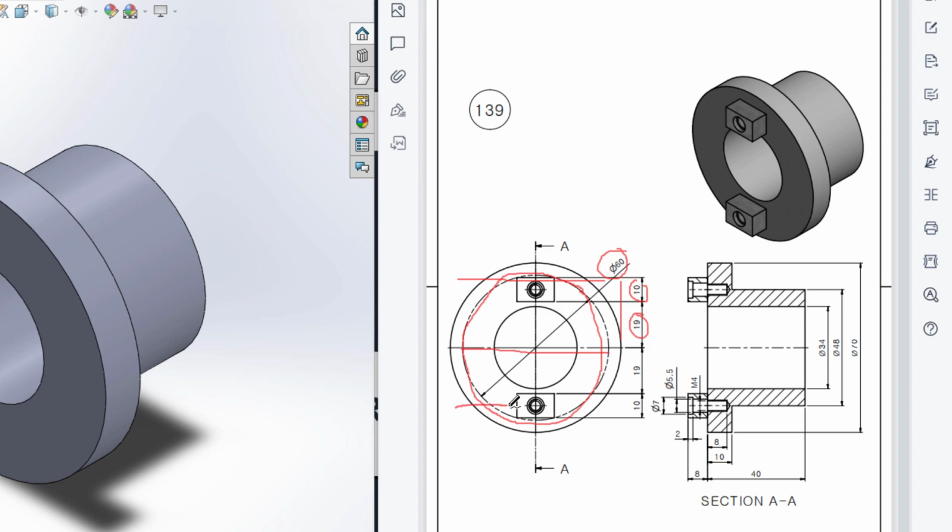I will also draw another offset line here, and this distance will be 19 plus 10 units. Then I will trim all the extra portion. After trimming, I am left with these two lines. Then I will offset again here and here. Then I will close the shape, and then I will extrude boss. For the extrude boss, we can see it has an extrude of 8 units.